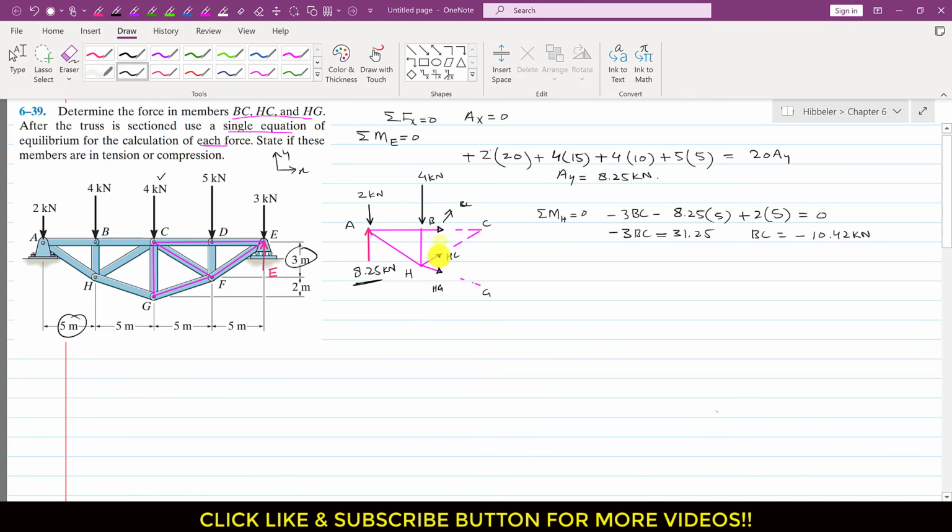The minus sign indicates that the assumed direction of BC is not accurate, since we are assuming that all these three unknown forces are tension forces, since these three forces are acting away from their respective joints, right? But the minus sign indicates that this BC is acting towards this joint B. So if it is acting towards this joint B, that means this is the compressive force, right?